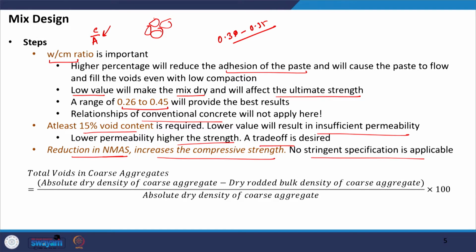Now, this coarse aggregate will then be filled with cement paste, or will be covered with cement paste, and then the area which is left here, this is basically the void which gets created. Alright. So, I am interested to see how many voids can be created. For that, I am first interested to see that the skeleton which I have chosen, this depends again on the shape characteristics of the aggregate, how much voids they create in between them.